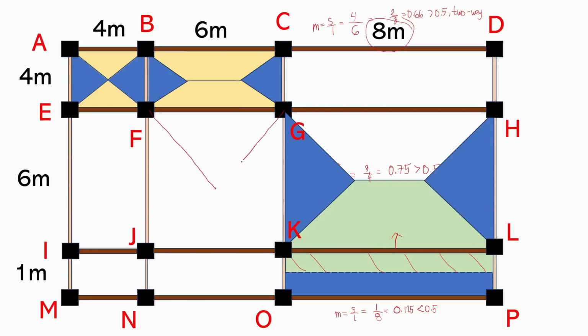And so, it will look like this. This will be the tributary area for this adjacent slab. Essentially, our tributary area for beam FG will resemble a diamond, because we will be considering this whole area. That is, trapezoidal plus triangular. And so that is our analysis there.